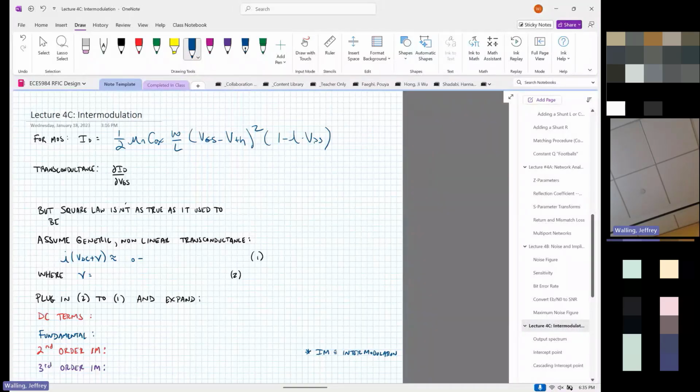All right, we're not going to write the square law for a MOSFET out too often anymore because, quite frankly, most MOS devices don't follow the square law any longer. At least none of the ones that you look at in this class will ever follow the square law. You're looking at 22 nanometer devices. Those are definitely not square law devices, but there is some exponent there, and it's nonlinear. The exponent is not 1.